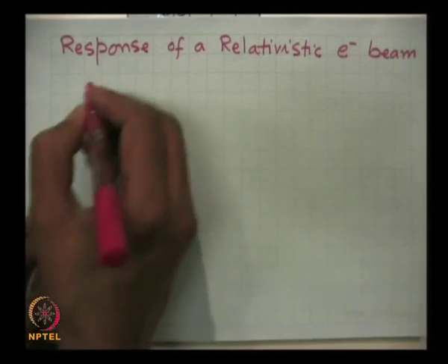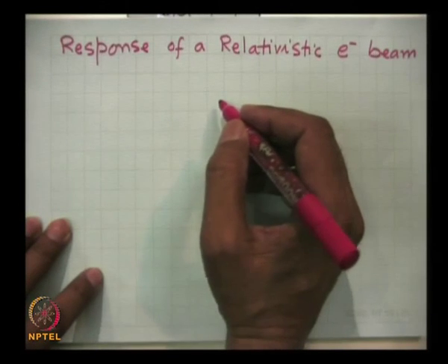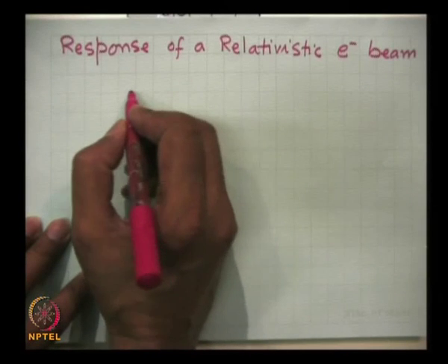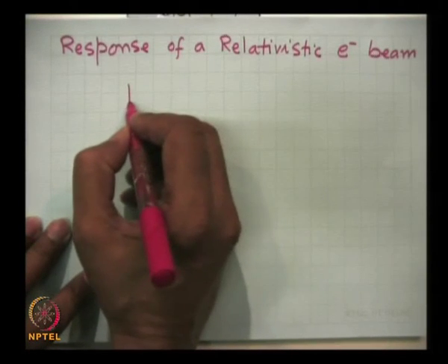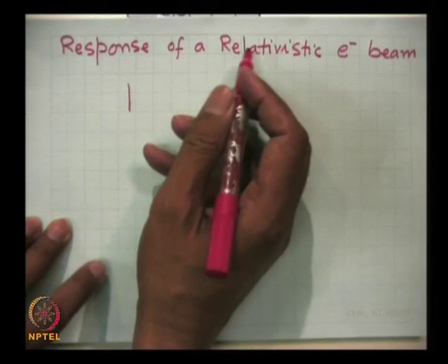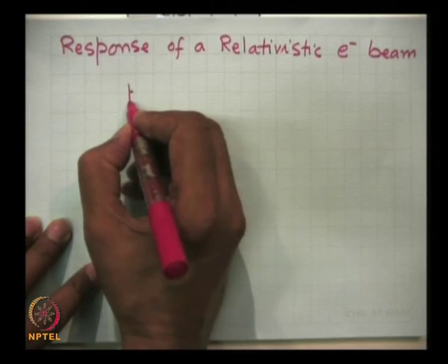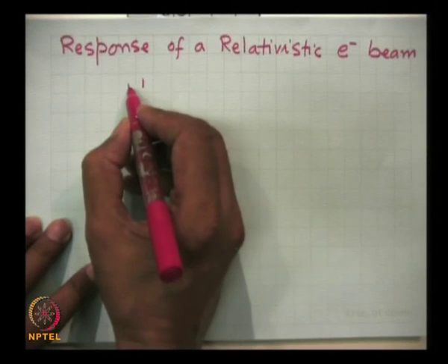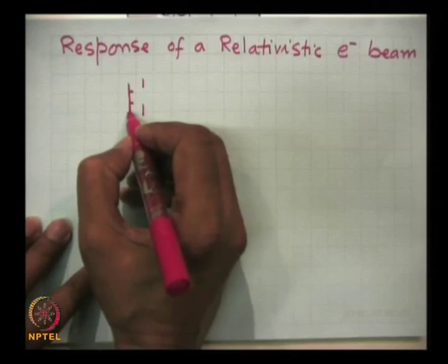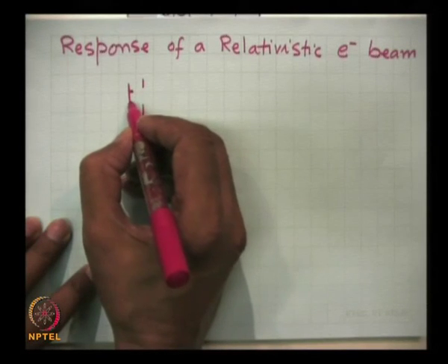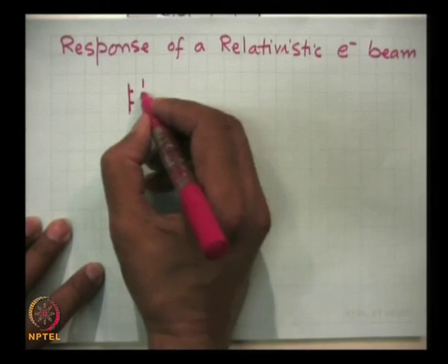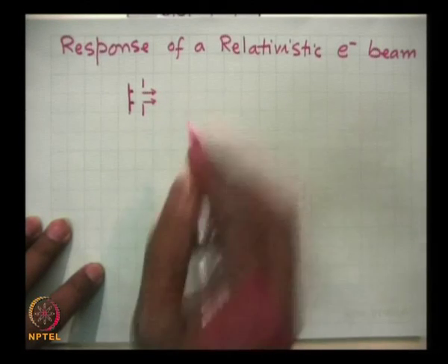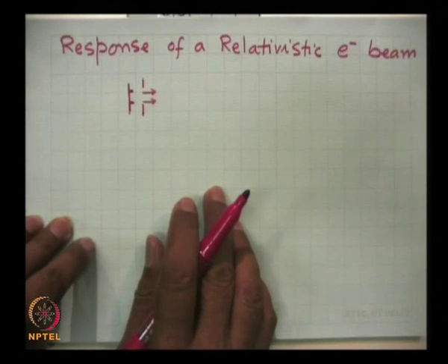Well, geometry is very similar, but the electron gun that you have to employ for this purpose is essentially a gun which can produce large velocity electrons, and a very special kind of gun is usually made for this purpose. As I mentioned yesterday, this is a gun which has a cold cathode with a circular knife edge, and that emits electrons. Usually the beam that you produce here is an annular electron beam.